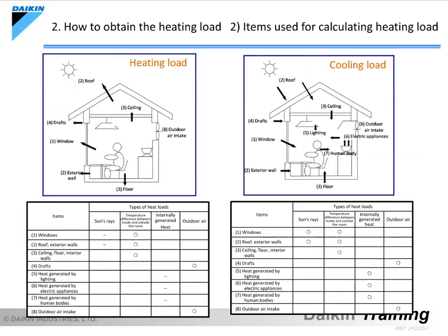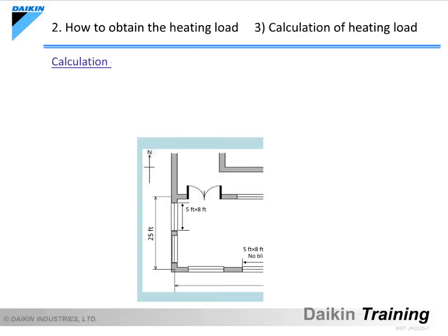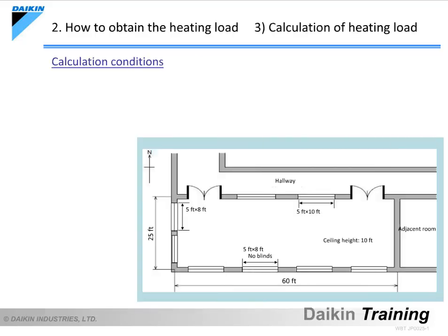The heating load is calculated in the same manner as the cooling load. However, the heat loads from the sun's rays and internally generated heat are not usually considered when calculating the heating load, because they provide heat indoors. These are the conditions for the heating load calculation.